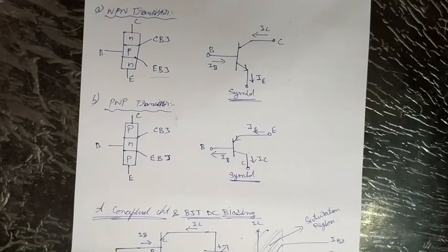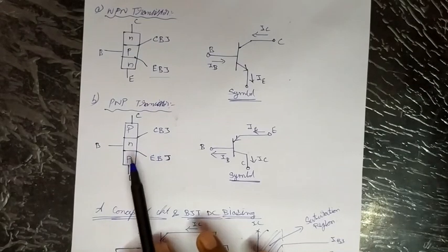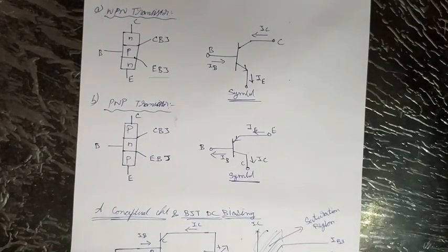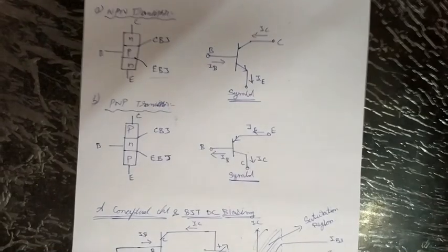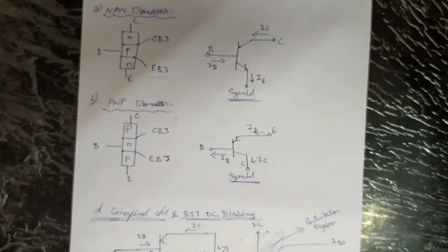Proper values of the two junction voltages can be translated equivalently into terminal current values, such as emitter or collector, which can alternatively be used to specify DC bias values of the transistor. The currents together with the bias voltage values of the junctions make the DC bias specification of a transistor complete.